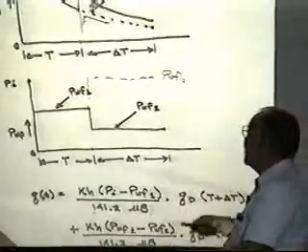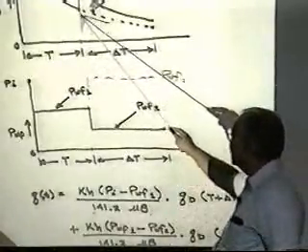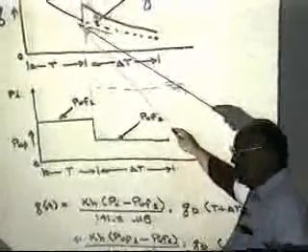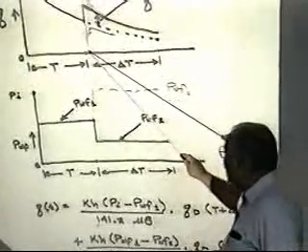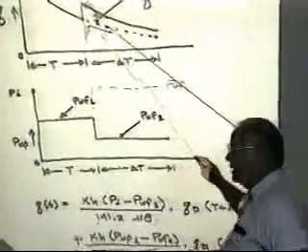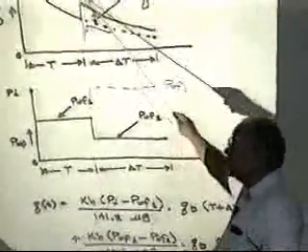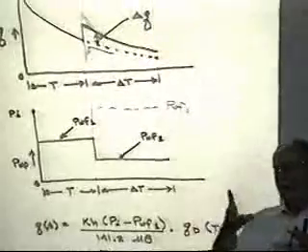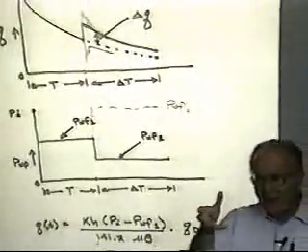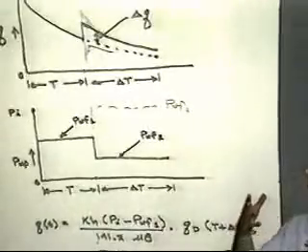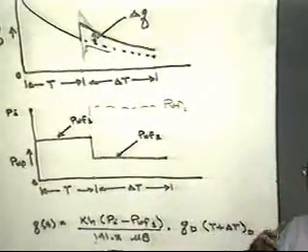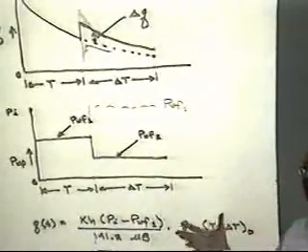With superposition, changes in sign, and you'll really see data where you have a curtailment by cutting a well back with a choke, where the rate's going to drop down and then it's going to come back again at a higher level. Exactly the inverse of increasing the flow rate due to a choke. So that when you look at the data, it looks like spurious data, like it has no meaning.